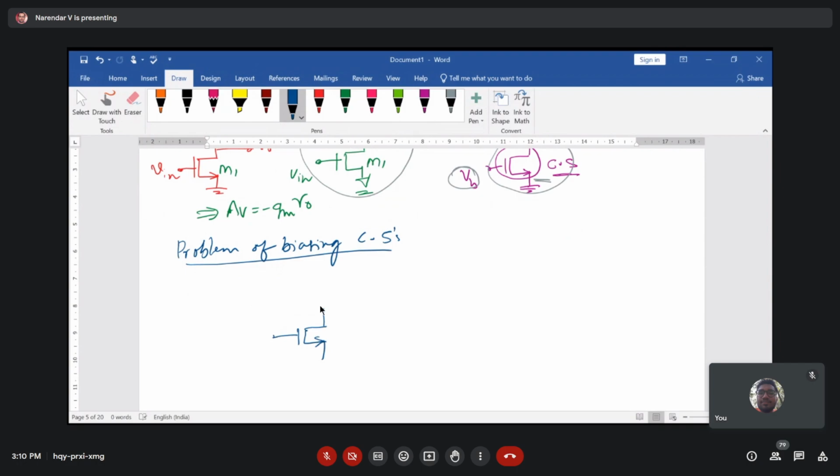This is the gate voltage that you have to apply. Now you have to ensure that the gate to source voltage VGS is a higher value, and here you have to provide the VB biasing. That VB biasing should contain the DC component, and you ensure that the drain current ID is constant when applying this VB voltage. So what is the relation between these two? The relation is that this VB voltage is the gate to source voltage, since the source is connected to ground. VB is your VGS value.